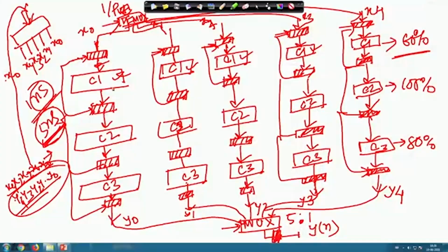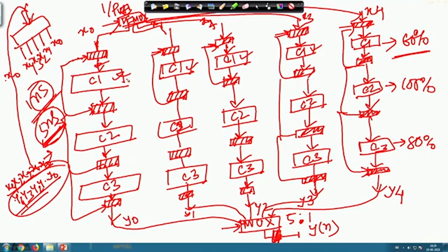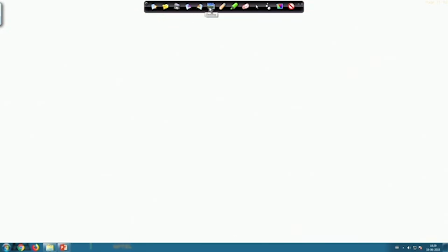I need this particular register to run at 3 nanosecond, this register to run at 5 nanosecond, and this particular register to run at 4 nanosecond. Okay. So, at that time I need the skewed clock which will be connected to this. If I just come down to that particular circuit, at that time what is happening? Basically, let me redraw the corresponding circuit.